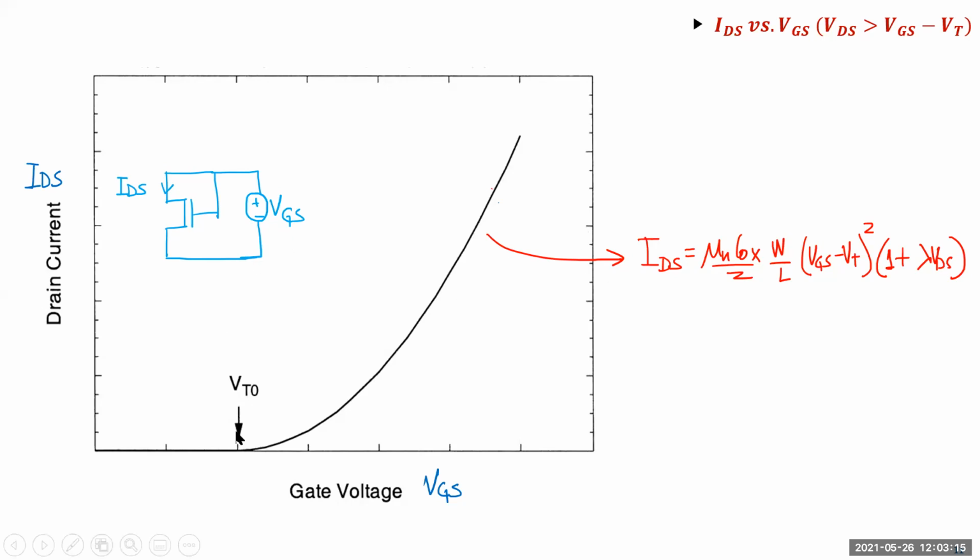So if you vary the voltage, you can see it's a square law. And this is what gives you basically the amplification. And if you remember in BJT, this was exponential, right? That's why BJTs are still used, as I was saying, if you need high-speed devices or large current devices for a given area, BJTs are still preferred. You get a lot of parasitic BJTs from CMOS, but good BJTs, you need this.